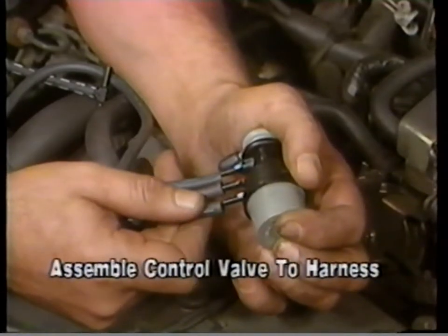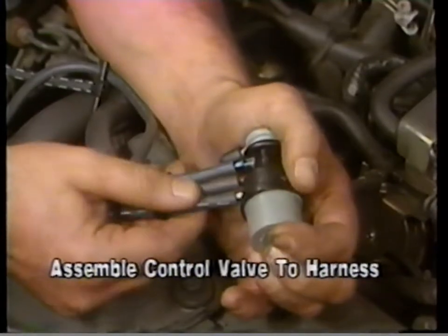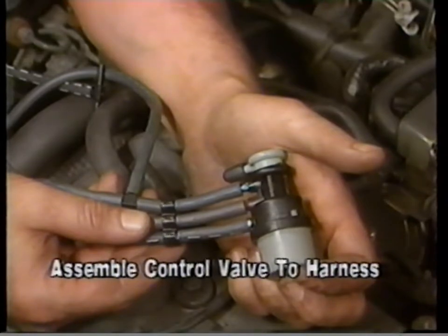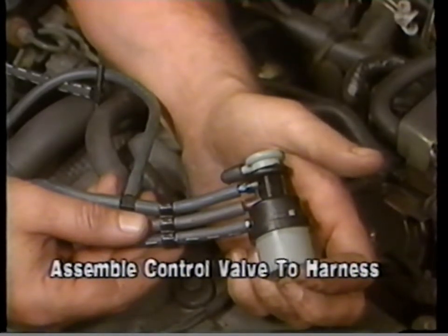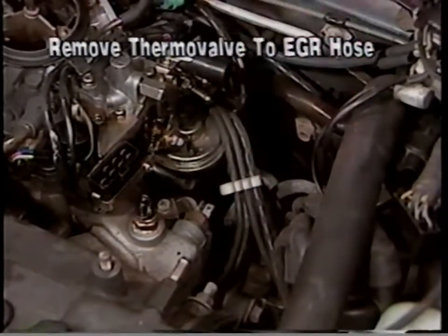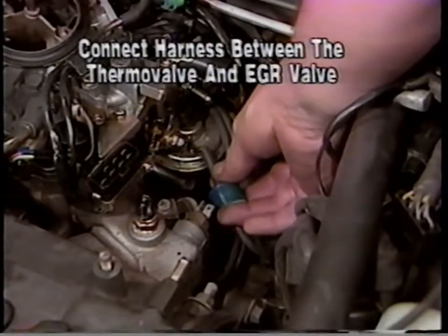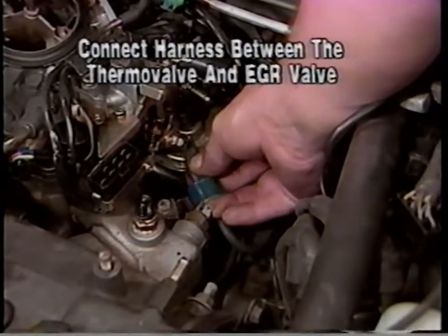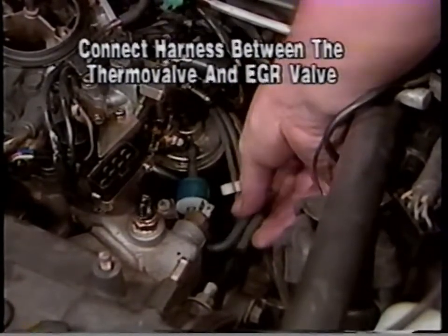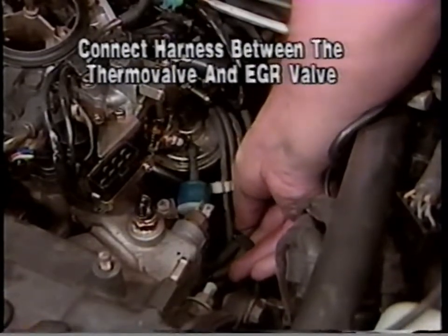To install the harness, first assemble the vacuum control valve from the parts package to the supplied vacuum hose harness. Match the blue, red, and white tracer hoses to the corresponding ports on the valve. Next, remove the vacuum hose between the thermo valve and EGR valve as shown here. Now connect the hose assembly from the vacuum harness to the ports on the EGR valve and the thermo valve. Connect the hose from the vacuum delay valve to the EGR valve. And connect the hose from the connector to the thermo valve.